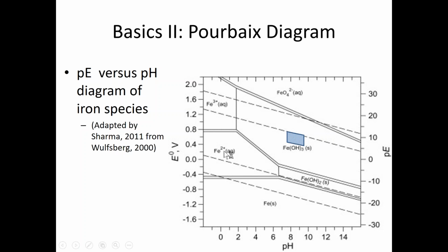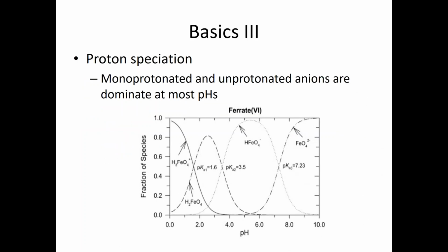And so there's a tendency for iron, of course, to corrode and form ferric and ferrous solids. And then just to fill out the whole list of different oxidation states, we have, a little bit above the metallic iron, ferrous iron, commonly the form found in slightly reduced groundwater. And then up here, ferric, and this is the form that we add as a coagulant, Fe+3. And so the ferrate is just another form of iron that wants to become ferric, and so it precipitates as ferric hydroxide in water.